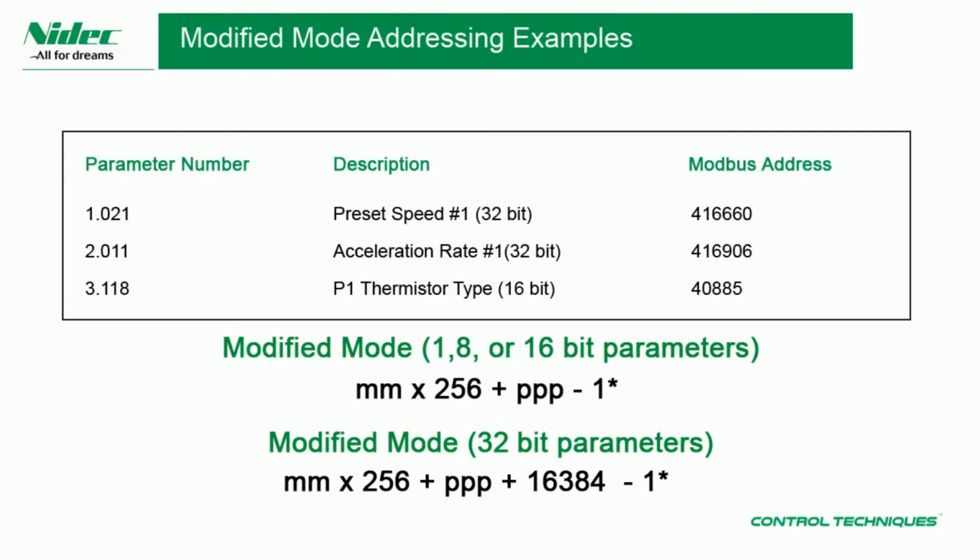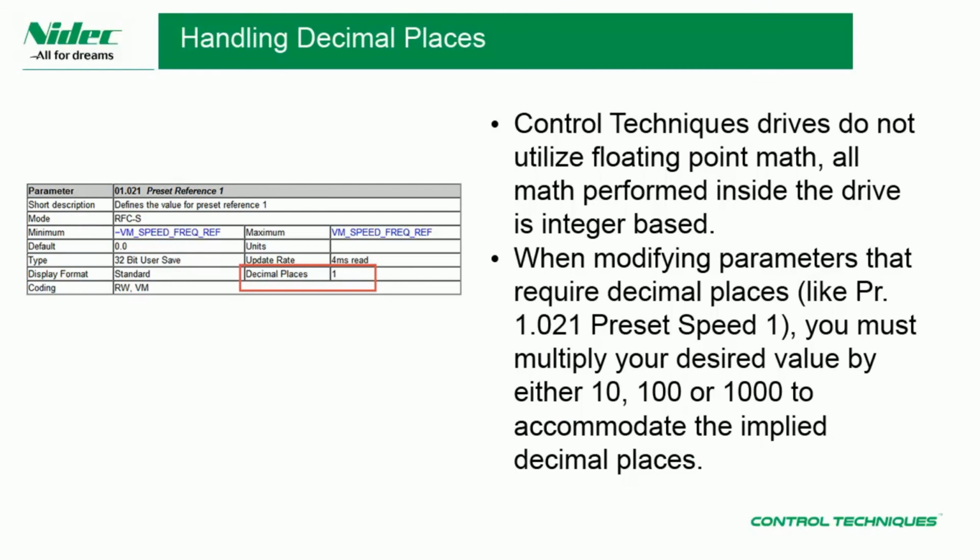If you're using a Unidrive M700, it is slot 4, menu 15, parameter 13. If you're using an SI Ethernet module, it would be slot 1, 2, or 3, depending upon where the SI Ethernet module is installed.